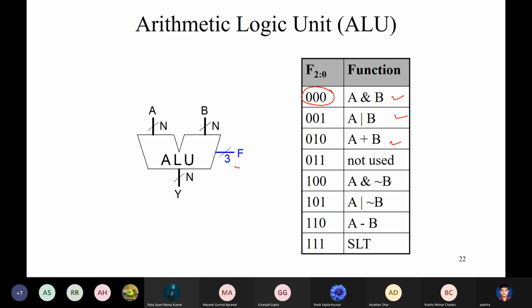To look at a simple ALU, these are the common functions. This is set left. I'm forgetting the name. Maybe one of the things we will study next is that each of these are simple circuits. You have logical and arithmetic blocks for each of these. They are all put together, and this F line, the function line, would choose which one would get activated.